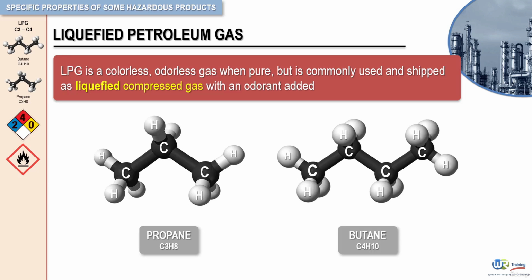Liquefied petroleum gas can affect you when inhaled. Contact with liquefied petroleum gas can cause frostbite. Very high levels of liquefied petroleum gas can decrease the amount of oxygen in the air and cause suffocation with symptoms of headache, dizziness, weakness, nausea, vomiting, loss of coordination and judgment, coma, and even death.